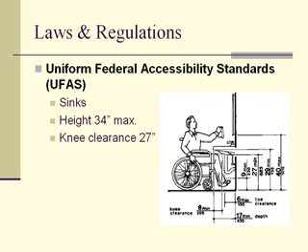Another element that has to be accessible in these lavatories is that if they have exposed pipes, there should be an element covering these pipes to avoid somebody either getting burned or cut by the pipes underneath the sink. So all those hot and cold water and drain pipes that are there should be covered.